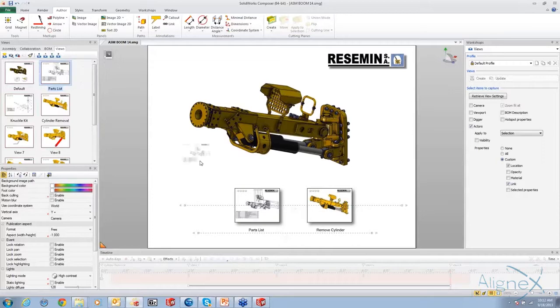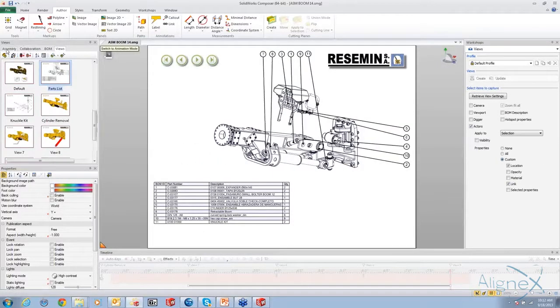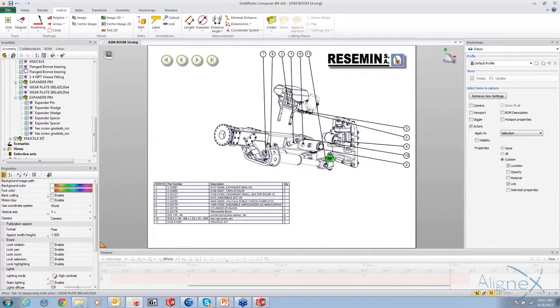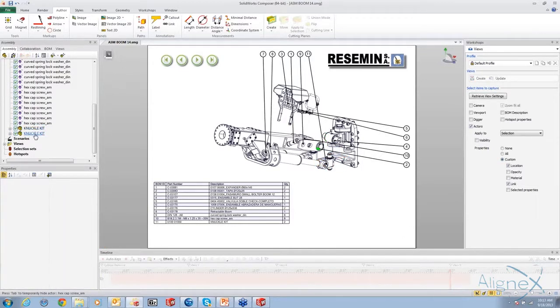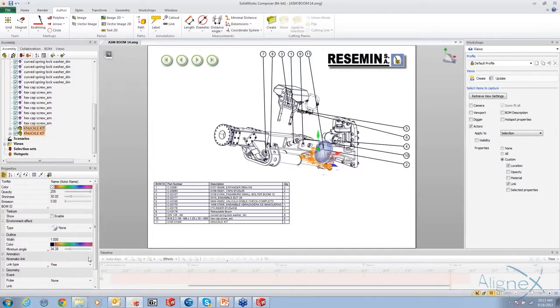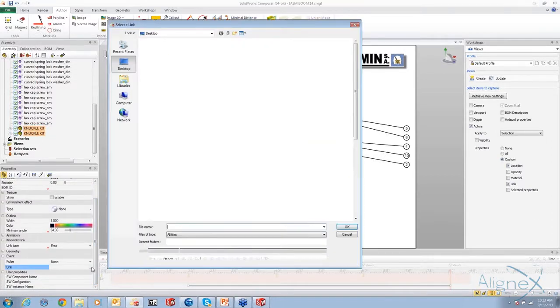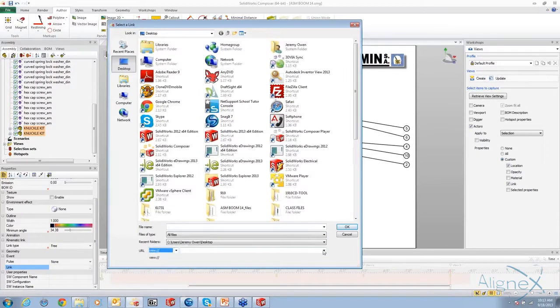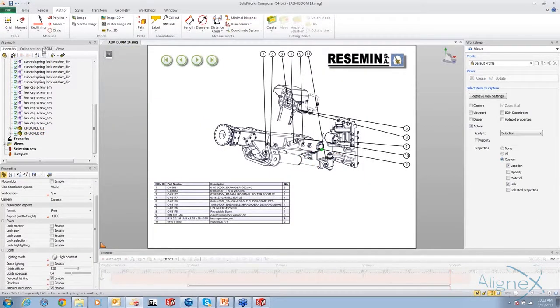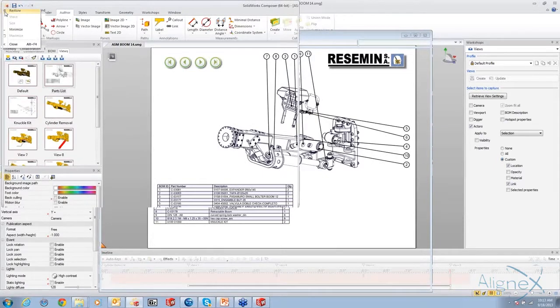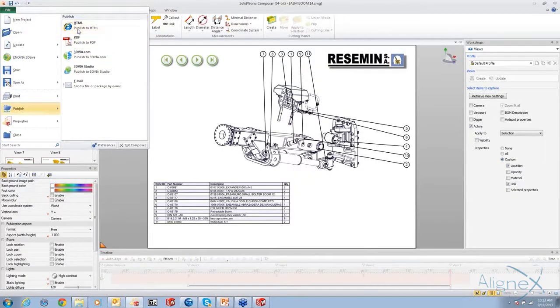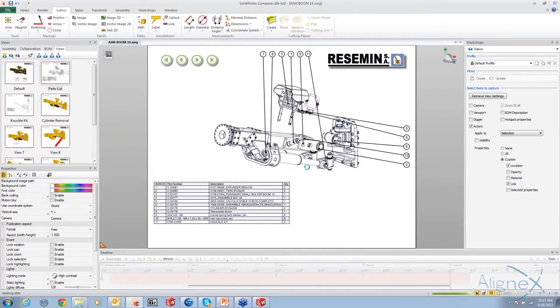And there's one more piece here. Let's go into our knuckle. We're going to select those two components for the knuckle there. Just going to select them right off my tree here. And we're going to link those to the other view of the knuckle itself. So we're going to link that to my view. Go to the knuckle kit. Okay. And then we'll update that view as well. All right, let's publish this out one more time. And then we'll go have a look at that.